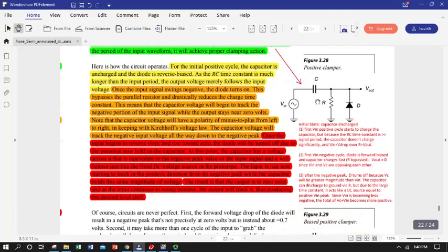Okay, one way we can do that is to use a capacitor. Because this capacitor is only going to develop a voltage that's equal to the charge it has on it. There's our definition of capacitors, right? The voltage over a capacitor is equal to the charge accumulated on the plates divided by its capacitance. So we're going to put a capacitor in this circuit, and we're going to keep our diode there. We're going to use a really big resistor, which makes this series time constant huge in the forward direction, where we would have to drive current in this direction to ground.